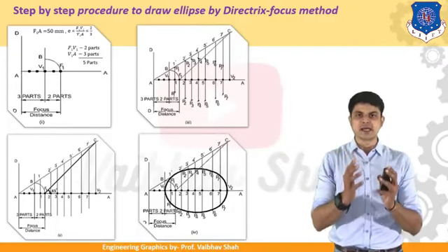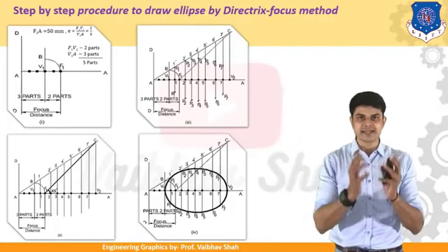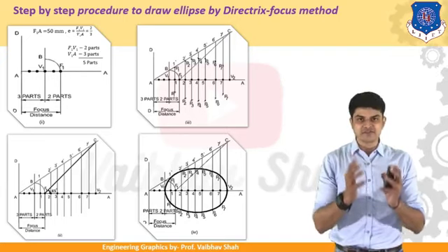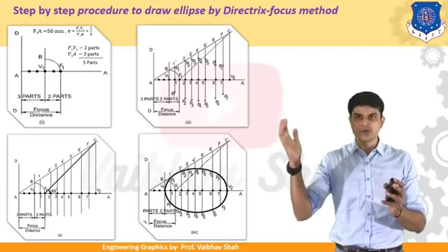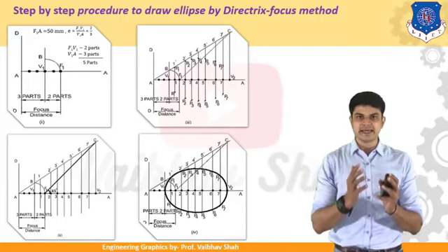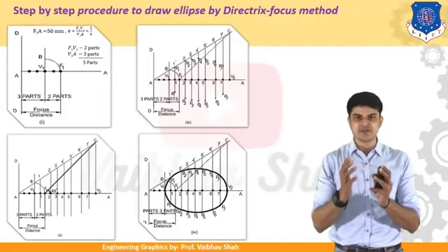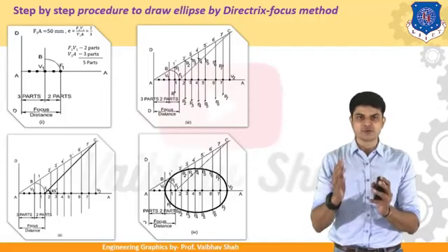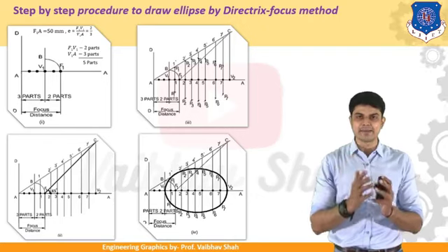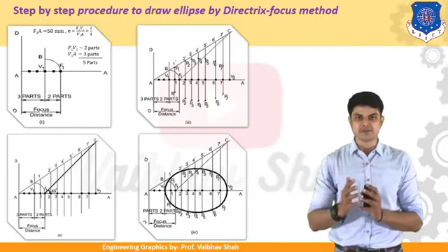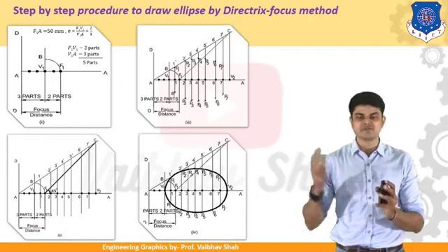So we'll be having a single part dimension which is nothing but 10 mm. So now we know that F1 V1 is equal to 2 parts. We should take 20 mm for F1 V1. So from F1 point, you should go on the left hand side for 20 mm and you will be having that point as V1. So let us mark that point as V1 first.